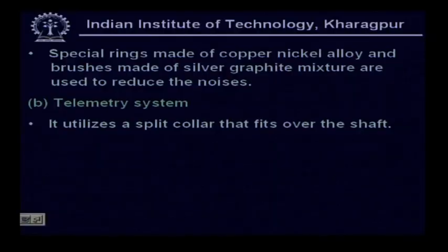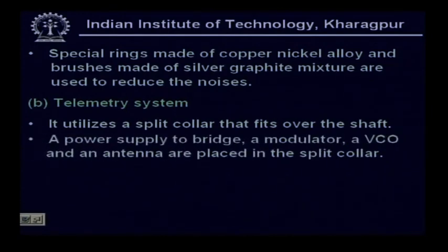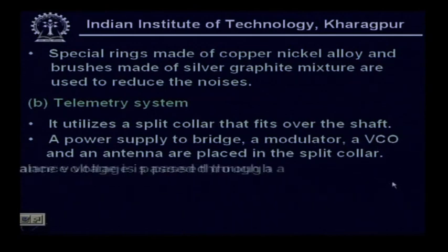Telemetry obviously means wireless telemetry. It utilizes a split collar that fits over the shaft. A power supply to the bridge, a modulator, a VCO, meaning voltage controlled oscillator, and an antenna are placed on the split collar.